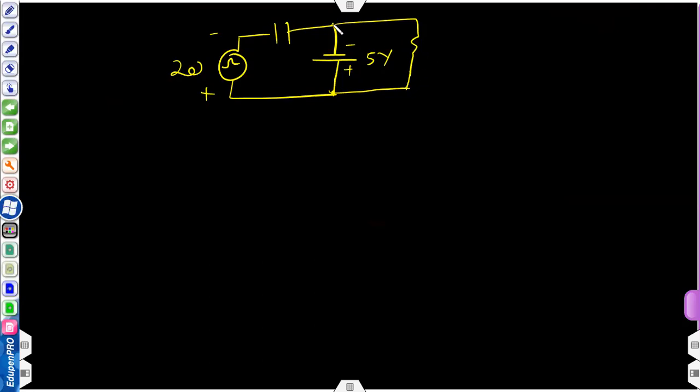Okay, so we have to ignore the resistor at this point, because we are interested in the voltage across this diode. This diode is connected to this capacitor, and this capacitor is connected to minus 20 volt. This is because of V in. This left hand plate is connected to minus 20 volt, and this right hand plate is connected to minus 5 volt. So you can see what is the net voltage.